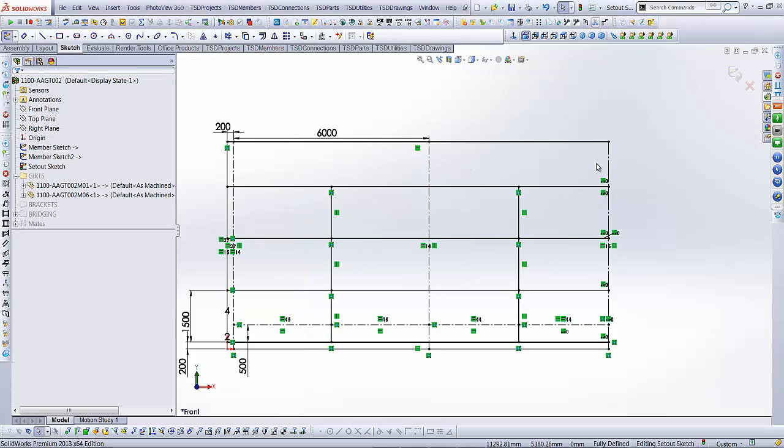Now maybe over here on the right hand side I've not done this right, because what I've got to do is, this is going to be an end bay wall. I need to set it up so that I can flip it. So it means that on the left hand side at the other end of the wall I've actually got an overhang past the column so that the girts come to the end. I need to do the same thing on this side, so maybe the trick here wasn't for me to extend this up, so I'm just going to do that.